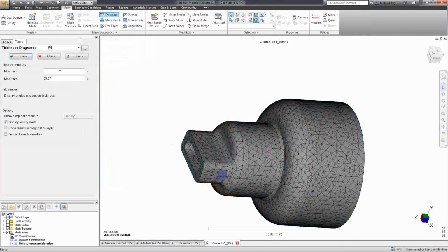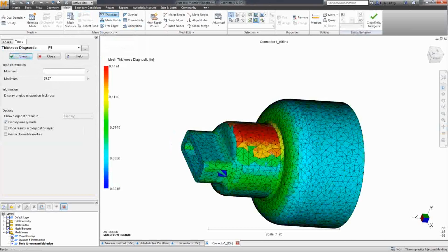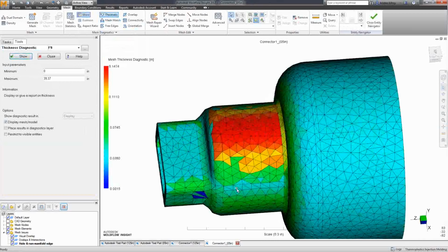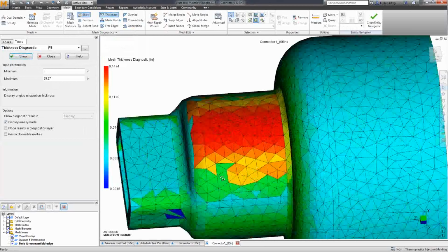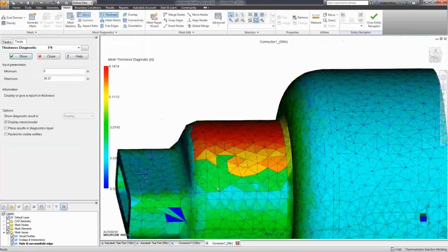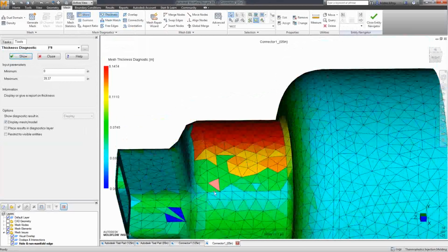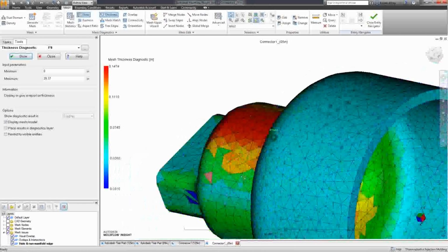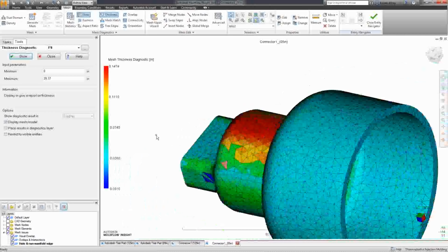Again, the thickness diagnostic can help too, showing you exactly what thickness it's capturing. Here we're seeing a measurement for that thickness, but since it wasn't matching with an element on the other side, it's going to be tough. It's really looking at the elements around it to help determine what thickness that is. And that's where error can be introduced when you're looking at your results. There could be some weird things happening in there.